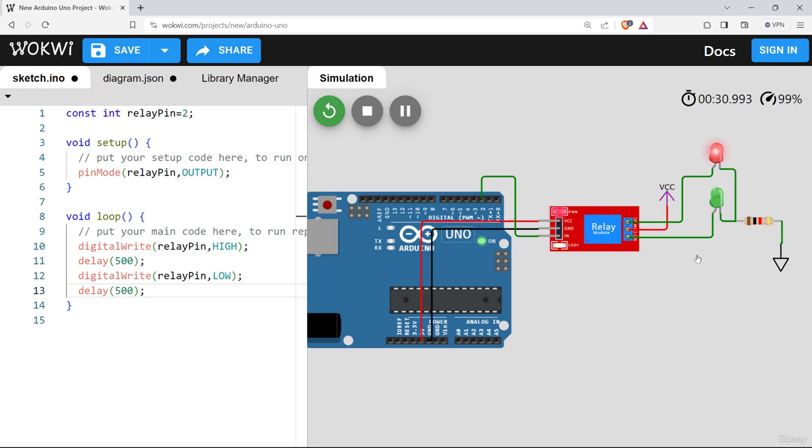So I hope you got an idea how a relay works, how we can connect Arduino to a relay, how we can configure the internal and external circuitry, and I hope these relay based projects will help you to unleash your potential to some more extent. We basically use this relay for different types of home automation, motor control, and heavy load automation, etc. Remember, on the relay input side, the power should be DC power, that is 5 volt.